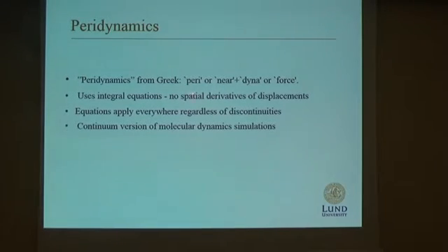It consists of two parts, where peri means near and dyna means force. What peridynamics is about is that we have a non-local force action between the material points. And since we have this non-local force action, we don't have any spatial derivatives of the displacement, as I will show you in the next slide, in the equation of motion.